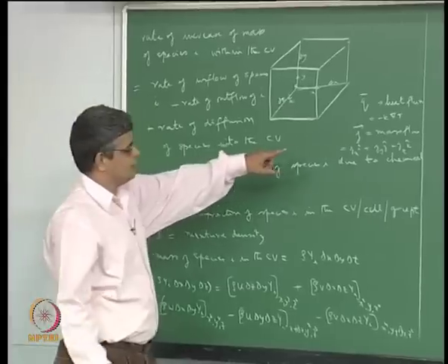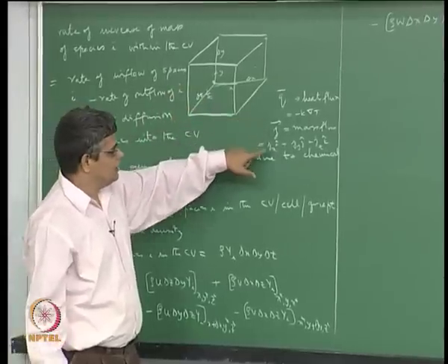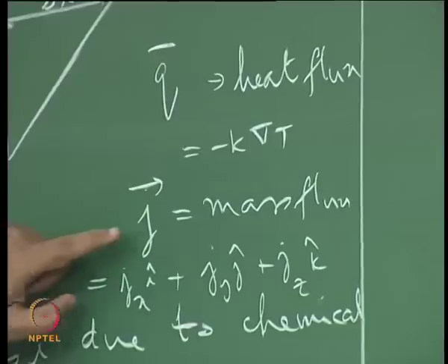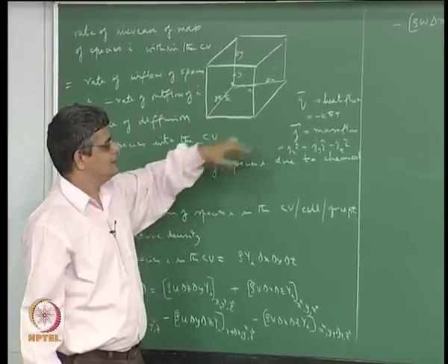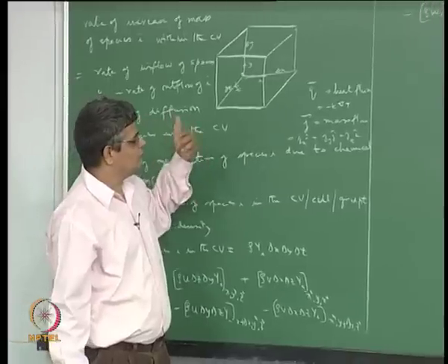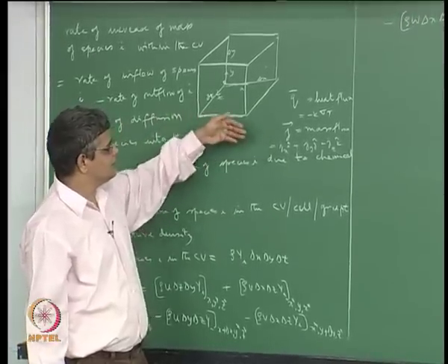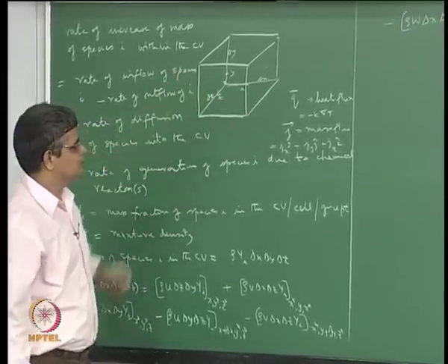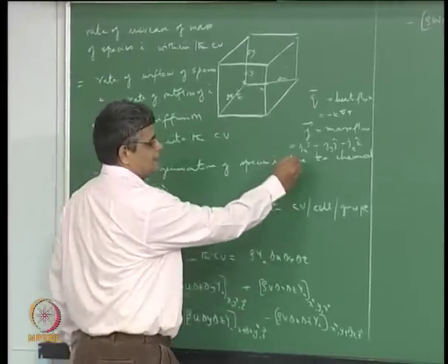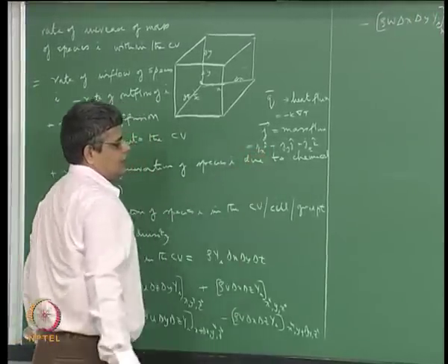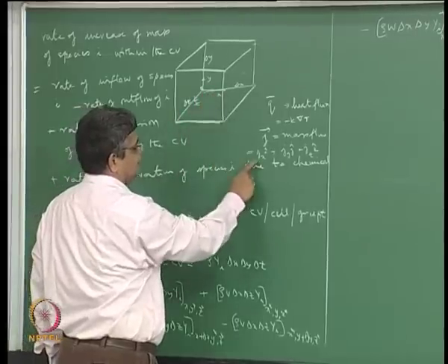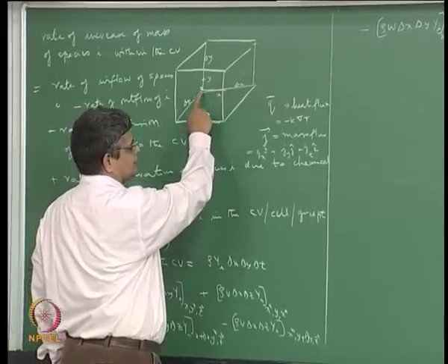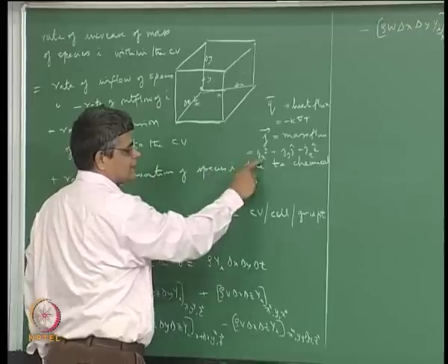Okay, so this is the flux at any point in the three different components, and the flux times the area normal vector. So J dotted with n is the actual flux that is coming in, the diffusive flux that is coming in or leaving the control volume. Okay, so now, as defined before, Jx is positive. When it is positive, it is flux in the x direction because it is the x component.